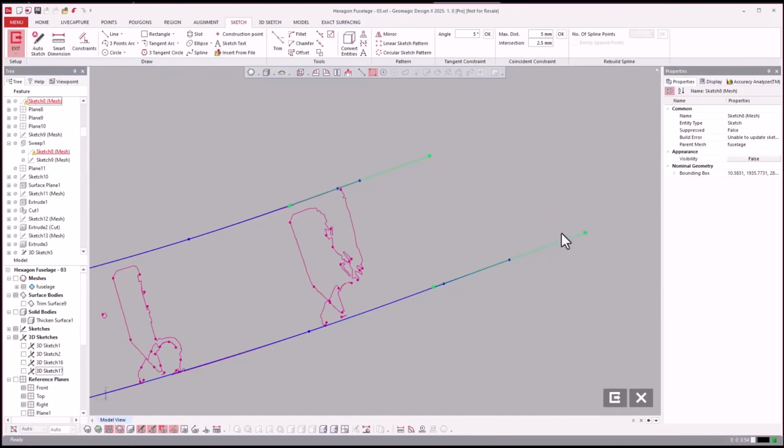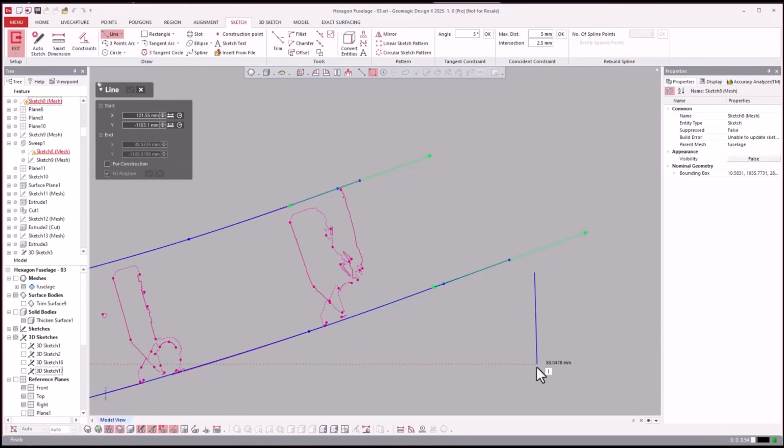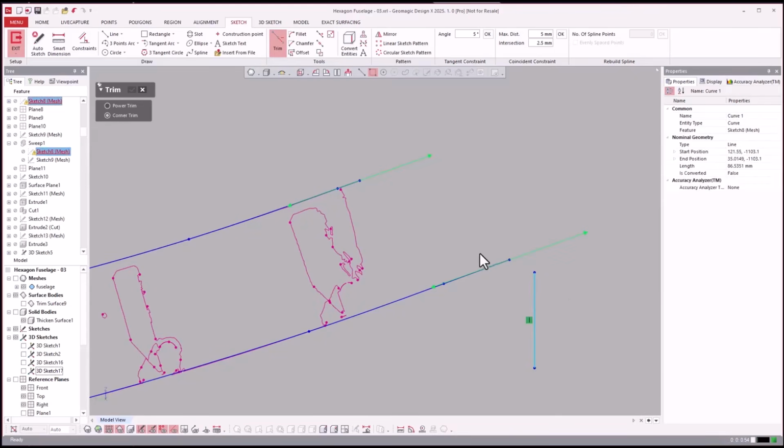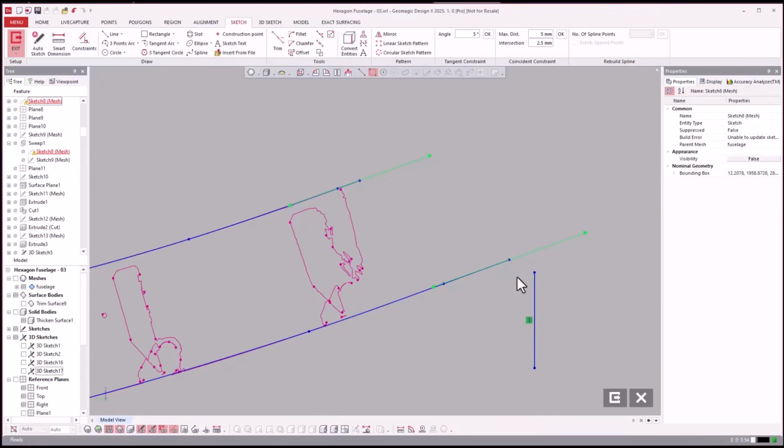corner trim as well. So we'll just do this. This is another method. I'm just showing that these exist. So if I had a line there, and I say I want to do a corner trim, still does not work, but the trick to it is go ahead and do an extend in that way, right, where you can come over and say extend up to.